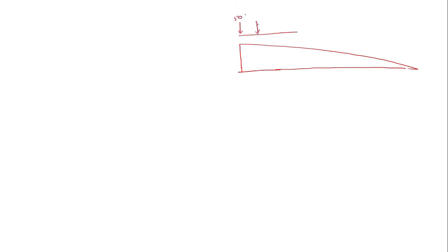Okay, next we go to find the third position. So here you have 50 kilonewton, 200 kilonewton and 100 kilonewton. If you find the ordinates here, this is 2 meter, this is 5 meter. So this length will be equal to 40 minus 7, 33, and this length is 5 and this length is 2.